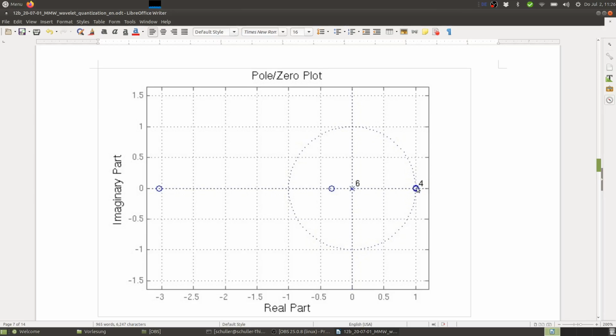And remember, pi in radians gives you this point. So then here at this point we have the Nyquist frequency. And if you go on to 2 pi, we get the sampling frequency. Then we just continue here and we land back at frequency 0. So basically one cycle gives us all possible frequencies.